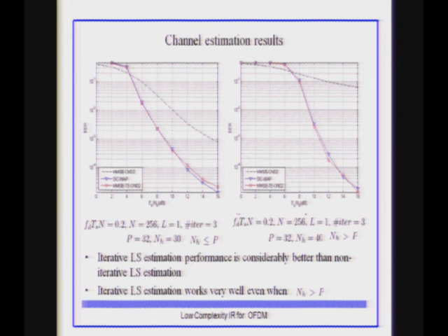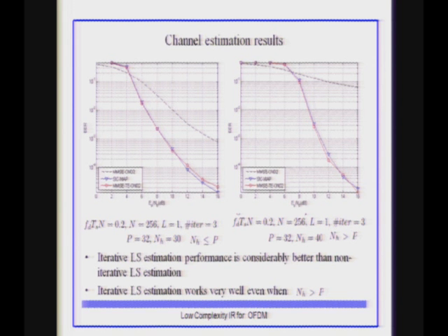And we are looking at the results after 3 iterations. So the iterative schemes work more or less the same, and the non-iterative scheme, the MMSE-based non-iterative scheme, is far worse because for the iterative schemes, after the first iteration, you get the mu's for all the symbols. So it's as if this one works with only pilot data. So you have only a few. Whereas these iterative schemes, after the first iteration, you have all the symbol mean values to aid your estimation.